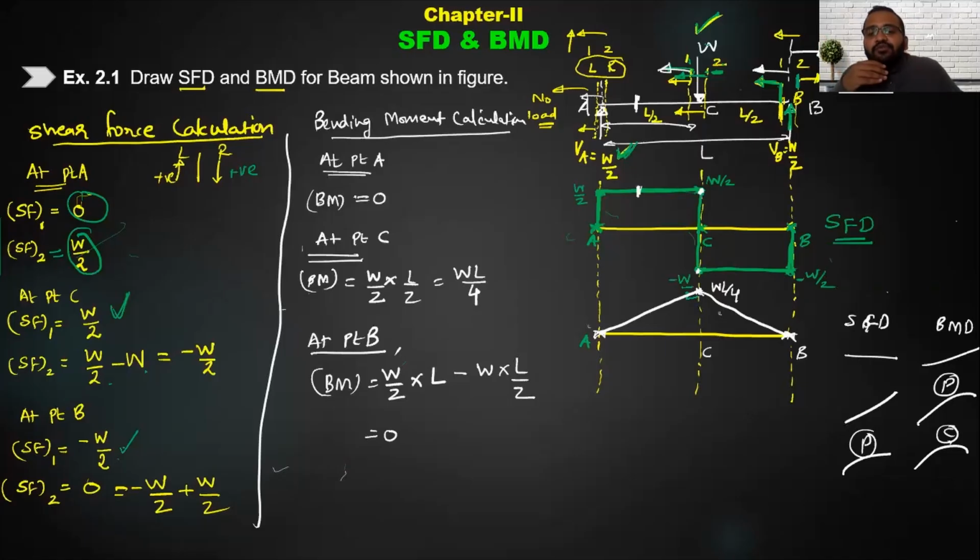So shear force and bending moment diagrams will enable us to know how the variation is going to take place across the beam. And suppose if I find that कि at point C सबसे ज़्यादा load आ रहा है, shear force आ रहा है, ठीक है, and उसके वजह से bending moment बढ़ रहा है, तो what I can do? I can make a different variation. Instead of having a uniform cross section beam, मैं C पे जहाँ पे ज़्यादा bending moment और ज़्यादा load आ रहा है, उधर मैं thickness बढ़ा देता हूँ. Instead of having a uniform cross section beam, I will take a cross section minimum at the ends and maximum at the center. Can I do that?